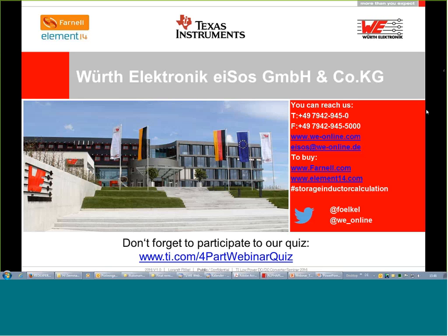It's not the same as having a shielding ring. I did a measurement myself with a near field probe, comparing the unshielded, the semi-shielded, and the shielded version in the same DC-DC converter with the same inductance value. There is a big step between the semi-shielded and the shielded version, but also in size.